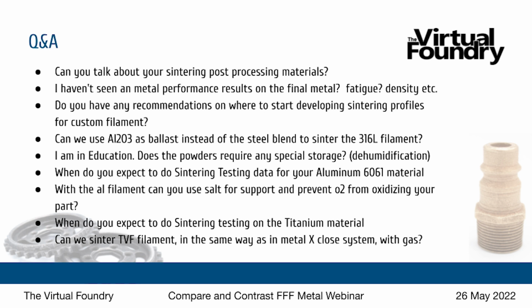In the post-processing, as they come out of the kiln, they look rough. They're not black if properly sintered. The copper will look copper-ish, but the parts are made out of microparticles of metal, so it has a pretty rough surface texture that corresponds to the shape and size of the metal particles in the 3D printing filament that you start with. Typically, we put them in a tumbler with some type of abrasive media like silicon carbide and tumble them for an hour just to clean it up. At that point, you don't have a mirror-like finish, but you have a nice clean part.